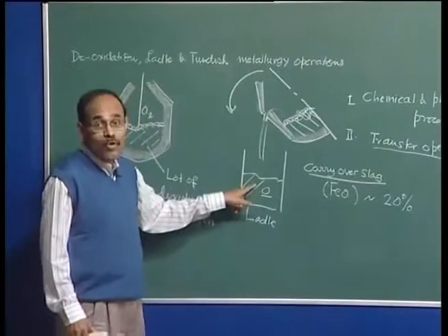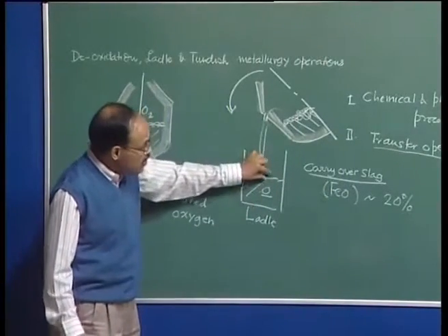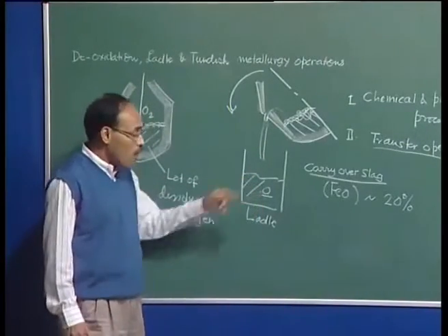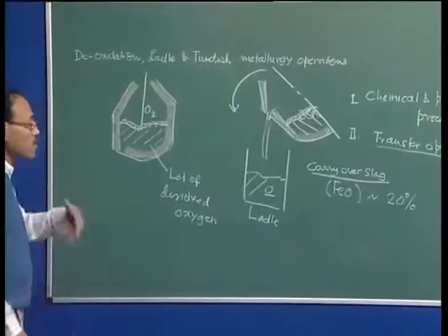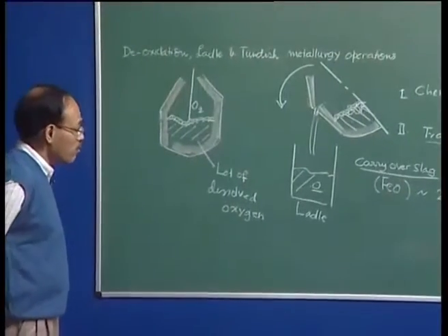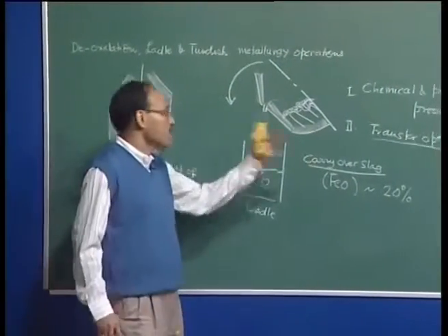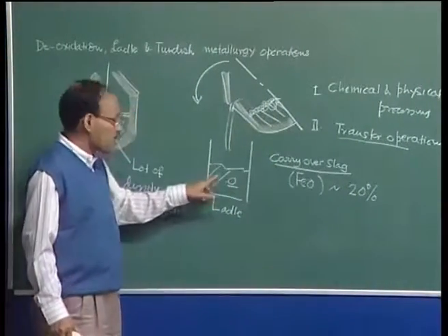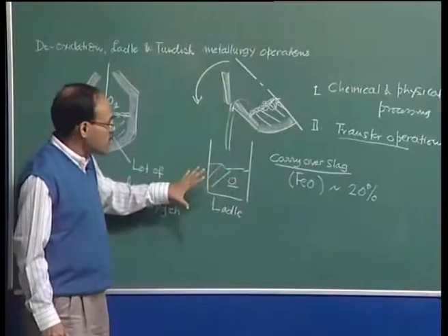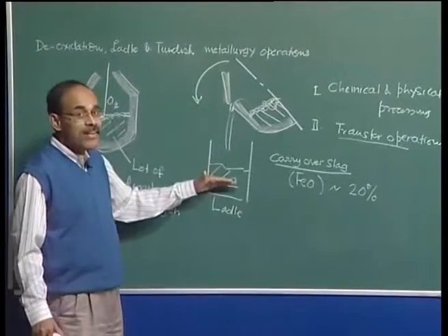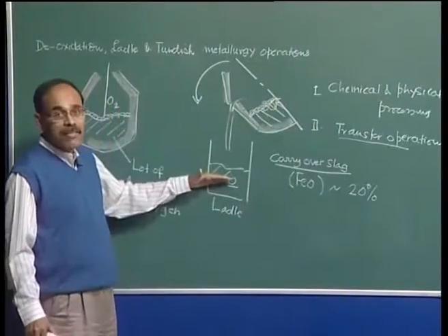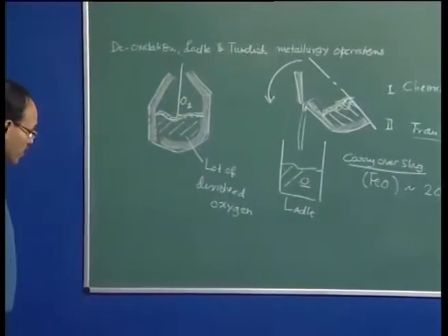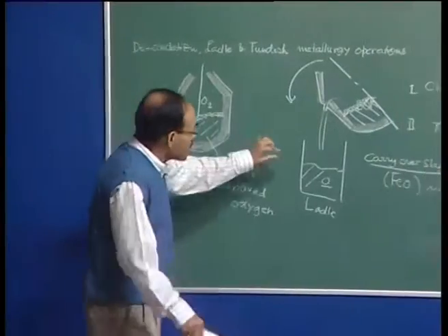We are not going to entertain any amount of this slag coming here, because we are now going to remove oxygen, which is essentially a deoxidation or reducing operation itself. So, the carryover slag, as we advance, we will see, influences adversely the properties of the steel. As a result, all subsequent refining reactions beyond the primary steelmaking vessels, which are going to be carried out in a ladle, are going to be carried out in the presence of a new slag.